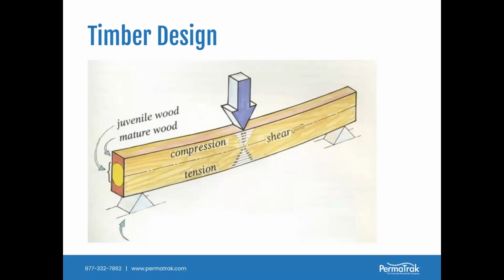Think about the wood framing in your attic. If you look at those wood framing members in there, they're probably going to have a lot of blocking and cross ties and diagonals to support them because they simply can't span that far. Like I said earlier in the presentation, typically a 10-foot span for a boardwalk is about as far as you're going to take some of these stringers. So there's a limitation on span, but there's a benefit of having the ability to go get these pieces readily available.